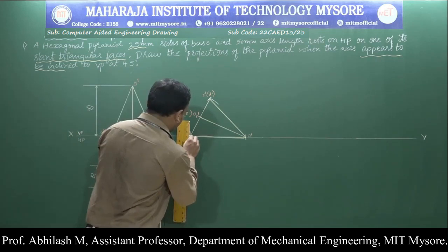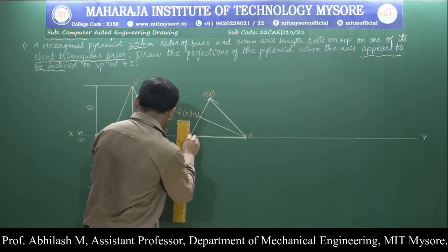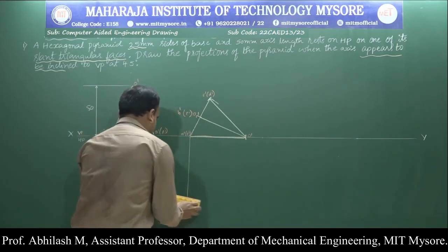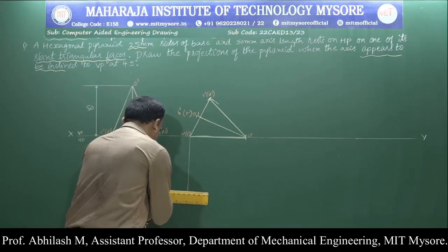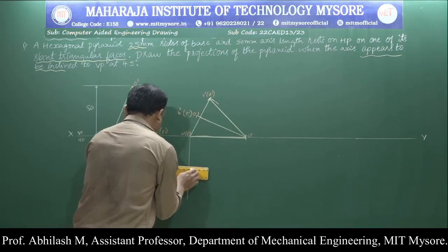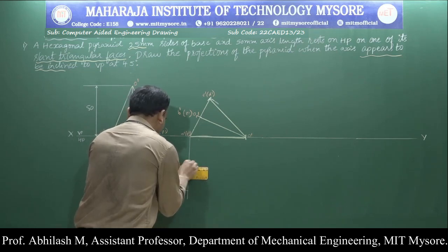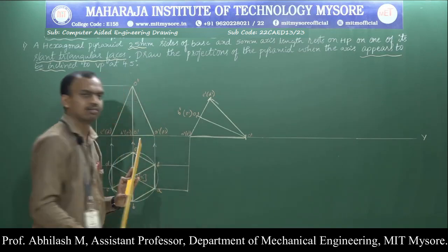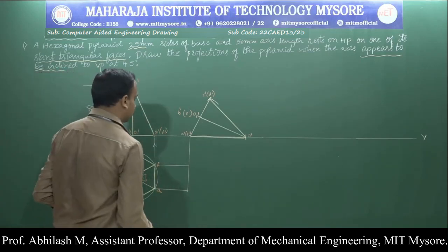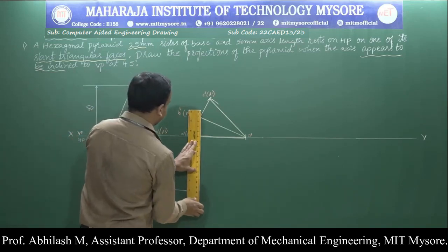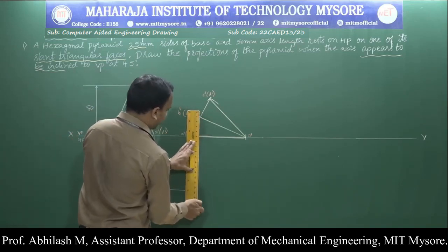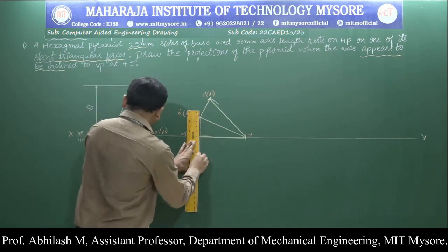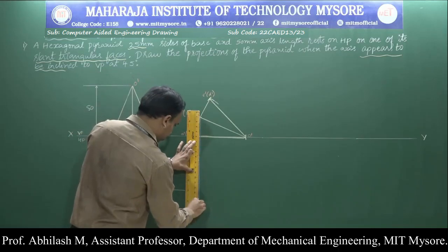From the corners of A dash of F dash, draw a line up to A dash of F dash, and connect it from the other end also, that is from A, similarly from F. Don't draw the excess line, it becomes unnecessary. Next we are supposed to go with B dash of E dash. So we will draw a line, B dash of E dash.